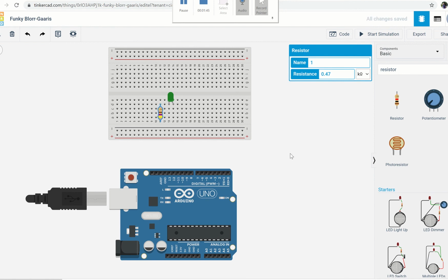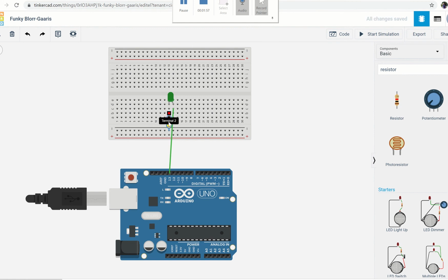Okay, so we're going to connect the wires, and our digital output is going from 13 to the anode of the LED. Then this resistor is going to be on the same row, but we cannot make it vertical like that, otherwise it's going to be shorted. So we're going to turn it and make one end the same row as this, and another one a different row. Now we're going to connect our wire to ground. Okay, so we have built our circuit.